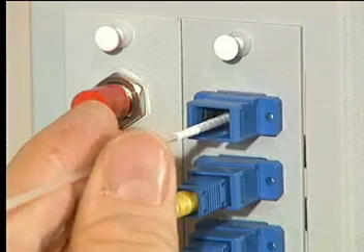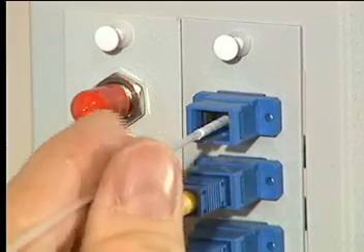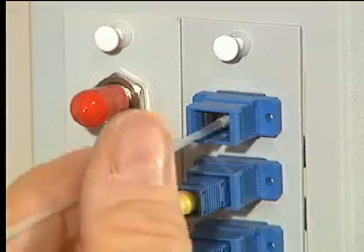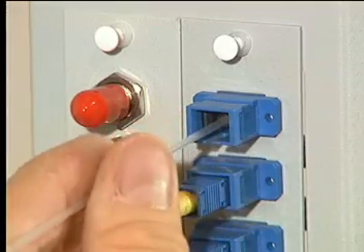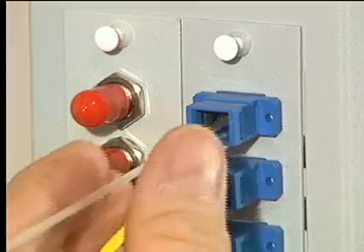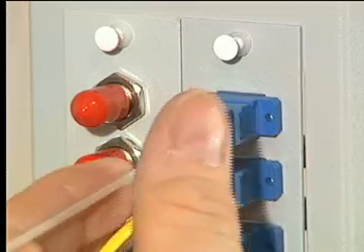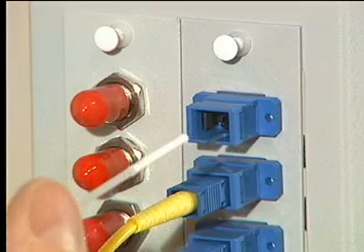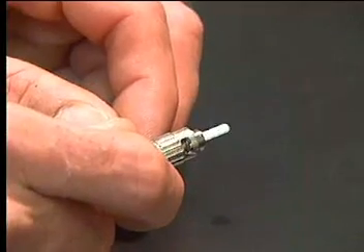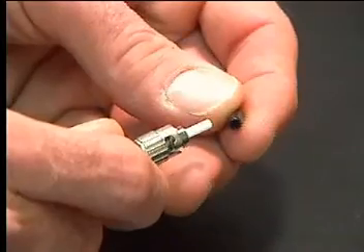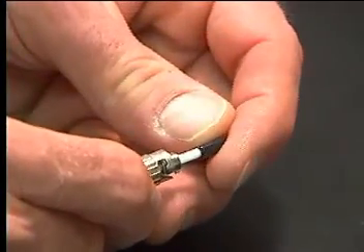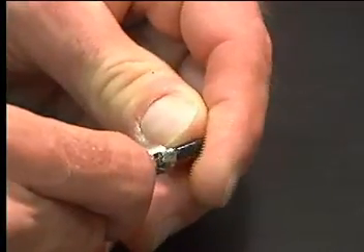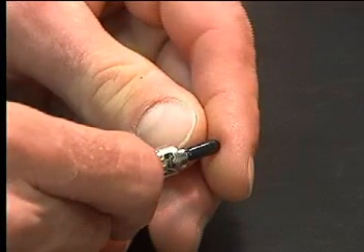Be careful of rotation when using swabs. Never rotate a swab that uses an adhesive pad to pick contaminants off a connector ferrule. Other swabs should be rotated clockwise to prevent the swab end from detaching from the handle. Consult the manufacturer's specifications if you are unsure. Always place a protective cover on the bulkhead or connector ferrule when not in use. But even if a connector is capped, it still must be cleaned just prior to mating.